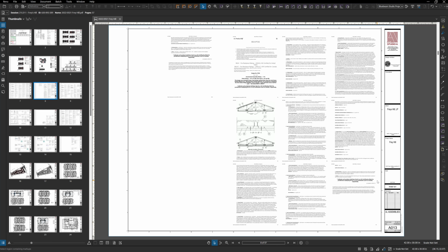And one thing that I see a lot of time, people dismiss the UL assemblies, or they just put them in, but they put the font so unbelievably small that no one could possibly read it, and then just leave it up to the contractor to go download the latest version, or they just have some version that's from like 2010, as opposed to periodically updating and checking these Underwriters Laboratories to make sure we're using the most current version of these assemblies. That to me is a big mistake.